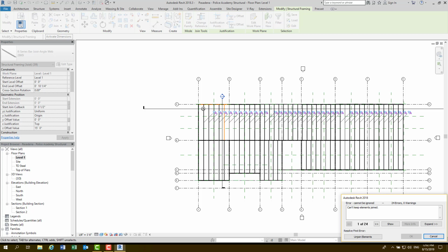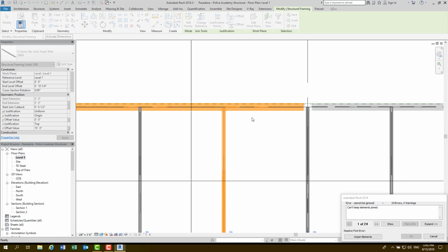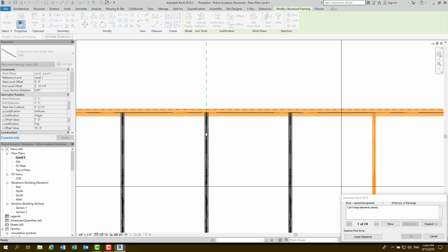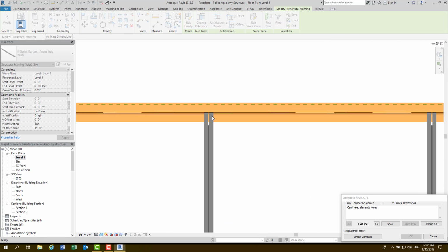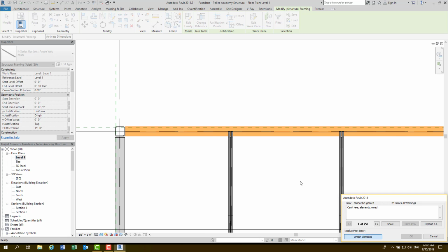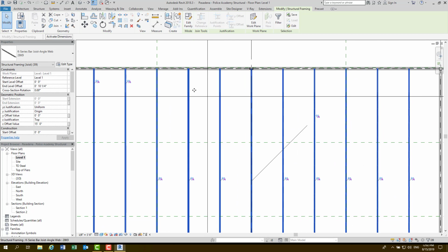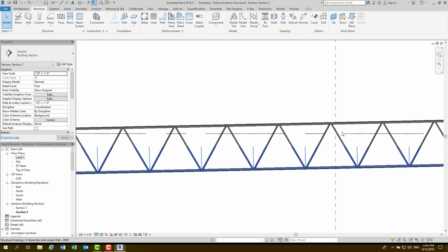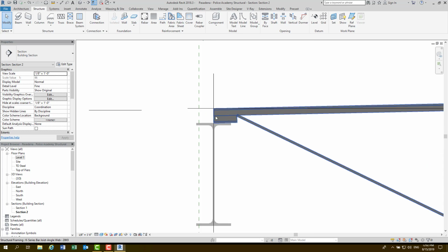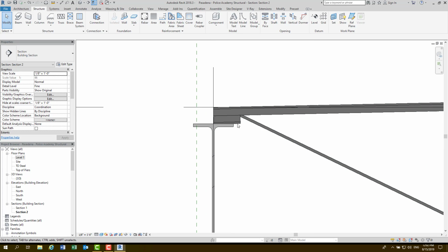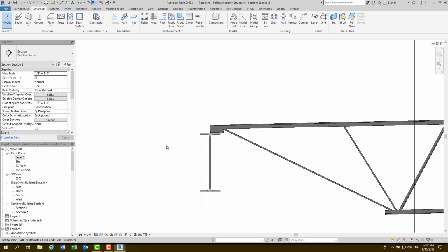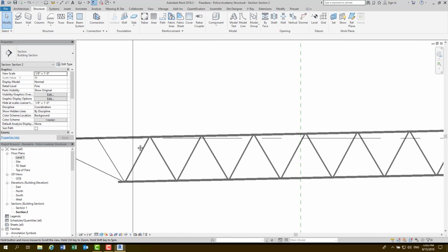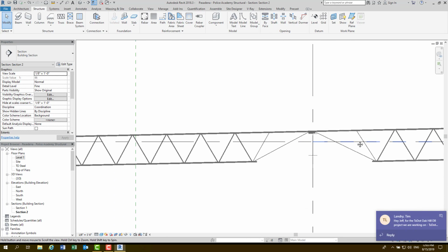Okay, so now we've run into a problem where it's saying that now we can't keep things joined because it thinks that it's now moving off the beam. So let's just, for now, say unjoin, because I want to take a look and see what that exactly means. So let's look at these and see how far off the beam did it move. Okay, so it looks fine. Really what that was is the beam system, which I didn't end up deleting. It thinks that the beam system got moved. And while technically it did, it got moved to where it was supposed to be.